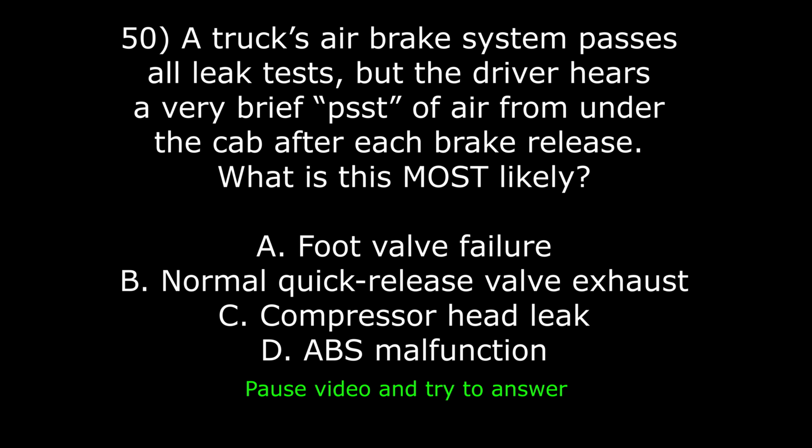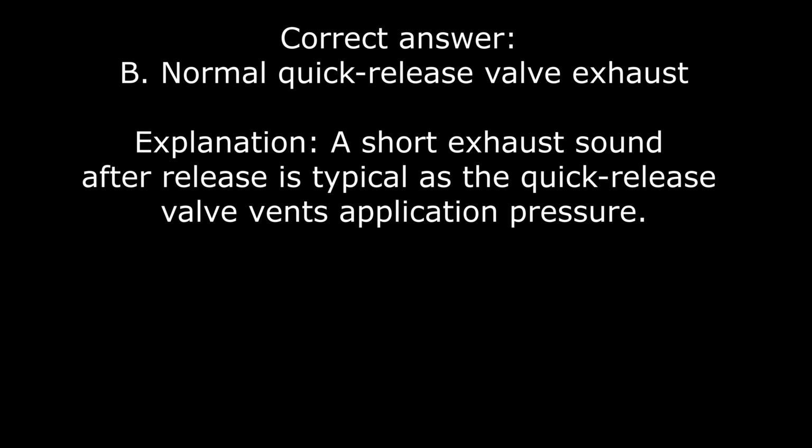50. A truck's air brake system passes all leak tests, but the driver hears a psst of air from under the cab after each brake release. What is this most likely? A. Foot valve failure. B. Normal quick-release valve exhaust. C. Compressor head leak. D. ABS malfunction. Correct answer is B. Normal quick-release valve exhaust. Explanation: a short exhaust sound after release is typical as the quick-release valve vents application pressure.